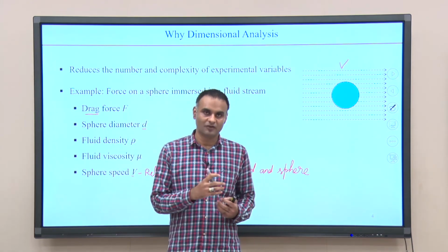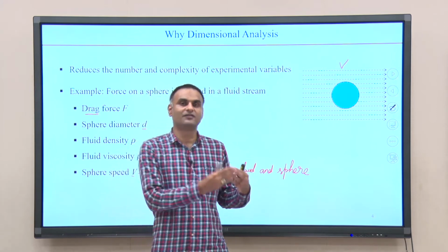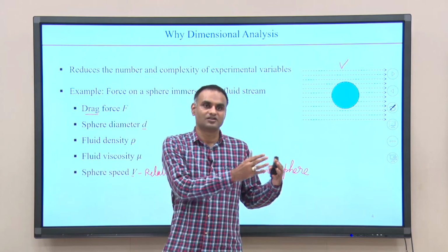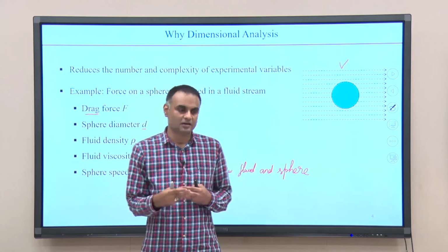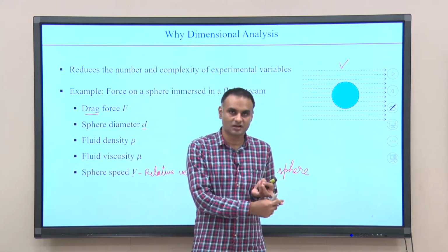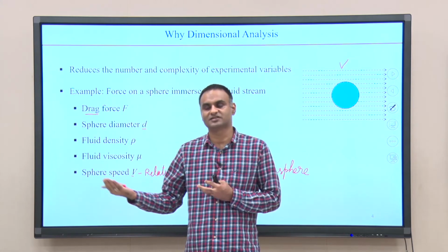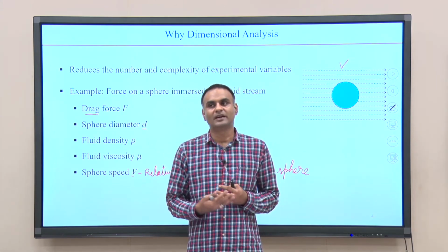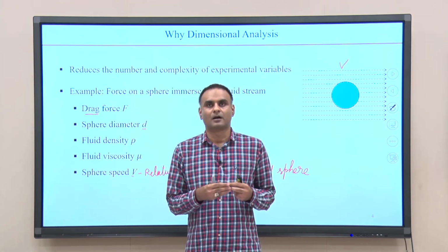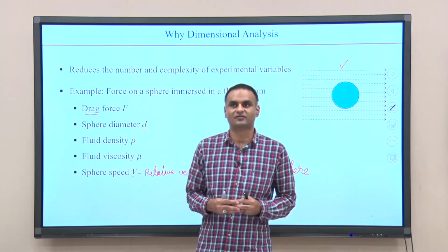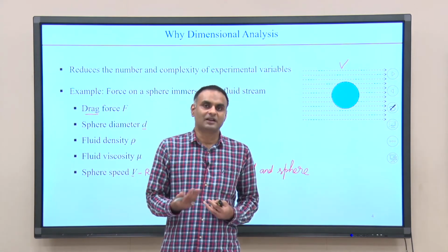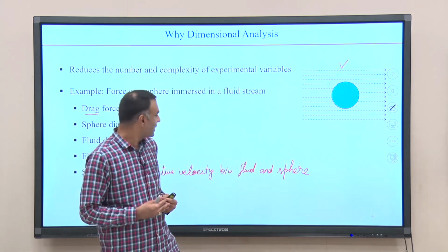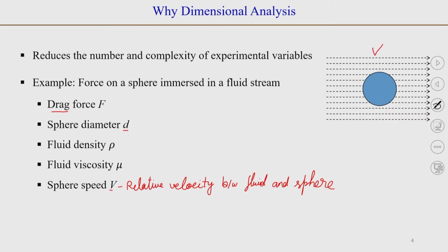Similarly, we will need to do the experiments with different fluids, then only will you be able to change the density. And the problem will come when you change a fluid, you will have changed density as well as changed viscosity, and moreover you might not see a large variation in density and viscosity and the parameters that you want to see. Similar is the case with the velocity. So, another way to do it is to group them in non-dimensional numbers.